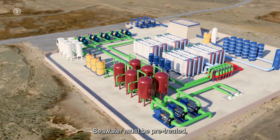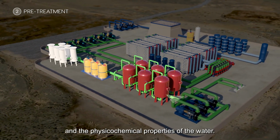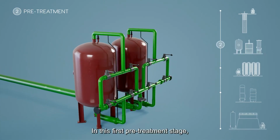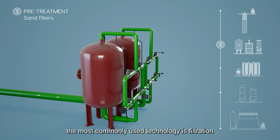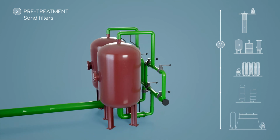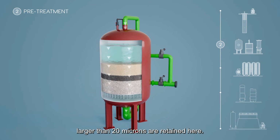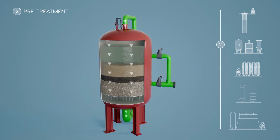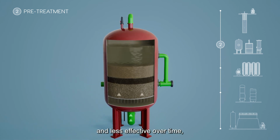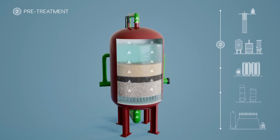Seawater must be pre-treated to a greater or lesser extent, depending on the type of intake and the physico-chemical properties of the water. In this first pre-treatment stage, the most commonly used technology is filtration, using substrates of different granulometry. Most of the suspended solids larger than 20 microns are retained here. These filters become dirty and less effective over time, which is why they must be backwashed periodically.